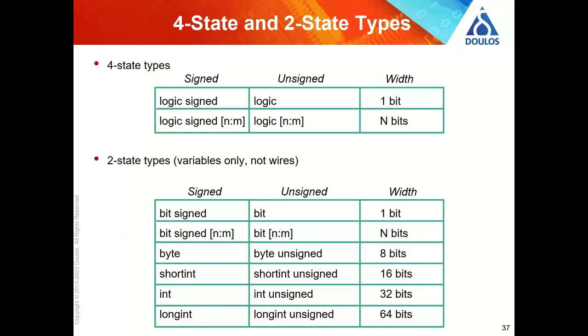Just out of interest, SystemVerilog has also simplified the way that Verilog represents states. Verilog doesn't really have a concept of a type. You have wires and variables, and you assign x's and ones and so on to them. In SystemVerilog, there is a logic type to represent that. So logic is for state. It can be signed if you want to represent 2's complement numbers, but there's also a 2-state type if you want to slim down the testbenches. If you don't need to worry about x's and z's, then you can just use bits. And then there are these other types which are 2-state, designed to map onto C. Those are particularly useful if you want to interface to C programs.